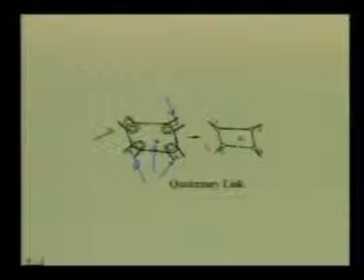This diagram shows how higher order links must be represented. Here, as we see, link number 2, 3, 4 and 5 are connected to a quaternary link which is numbered 6. Since link number 6 is connected to 4 other links, this is a quaternary link. In the kinematic diagram or the line sketch, if it is represented like this, then there is ambiguity.